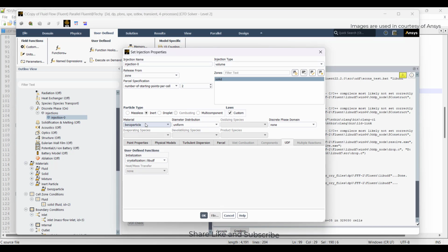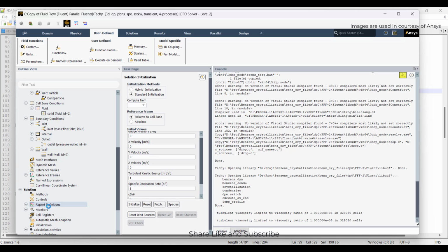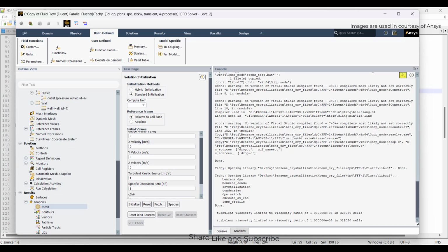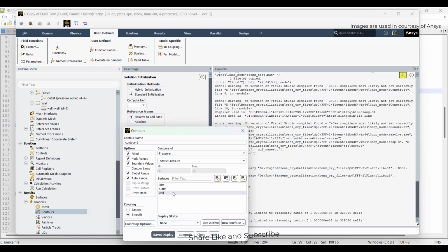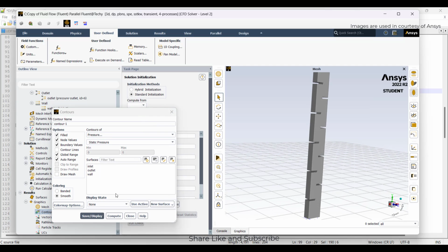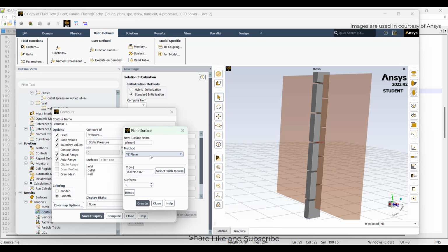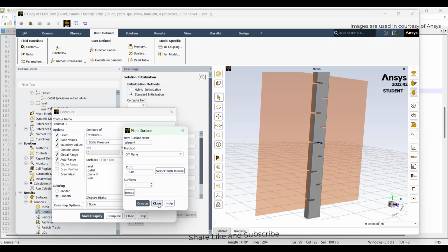It's benzene particle. If it meets the criteria of pressure by sublimation pressure greater than 1, benzene vapor will now be initiated with this benzene particle. According to this UDF, the particles will be injected into the domain. Now we have initialized. After initialization, you can just check how exactly the species fractions are. So maybe I'll select an XY plane, XY plane, create.